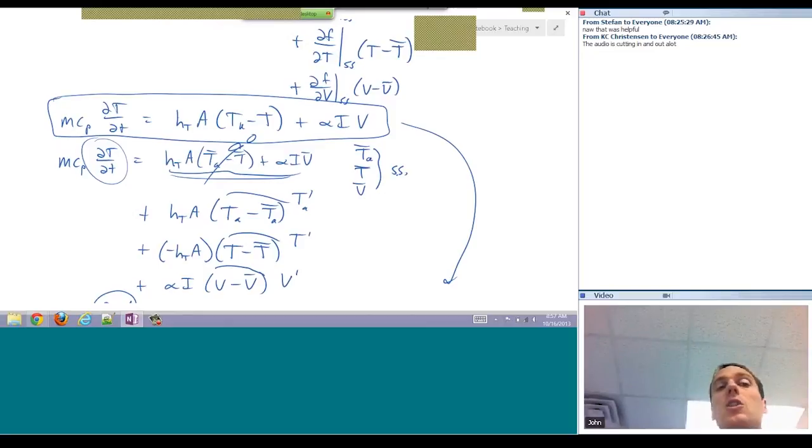Now, you also have a heat transfer coefficient. Let's say I wanted to not have to estimate the heat transfer coefficient when I'm trying to estimate alpha, because the two are going to kind of compete. You don't know which one. If the heat transfer coefficient is higher and the alpha is higher, you get more alpha dissipating it more quickly, or not. What could you do to your system to try to isolate the value of alpha?